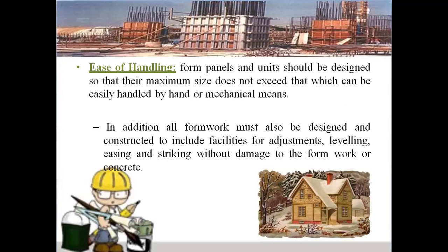In addition, all formwork must also be designed and constructed to include facilities for adjustment, leveling, easing, and striking without damage to the formwork or concrete. In the formwork we arrange, there should not be undulating surfaces, and the surface should be leveled properly.